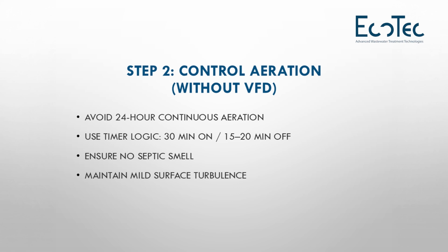Other things to observe are odor. Observe the mixing. You can see the sludge behavior. And if everything looks okay, then probably the plant is also functioning okay. You still have the water to test. Look at the water, and if the water is clear, which means the treatment has worked.